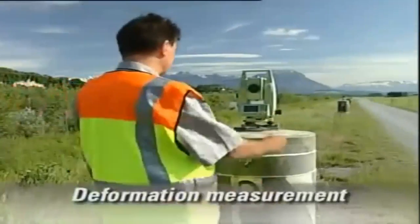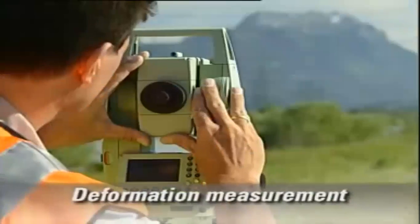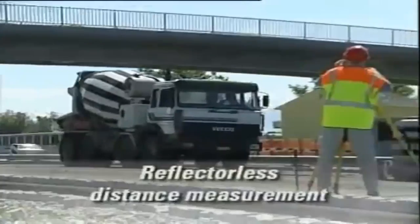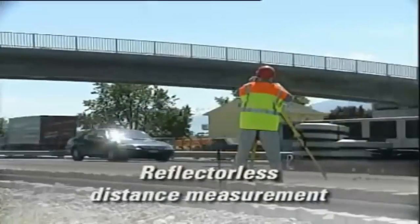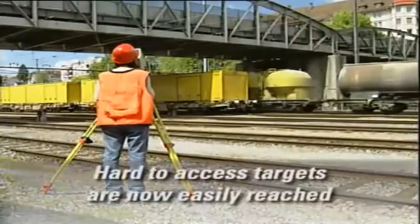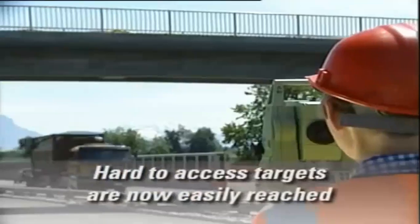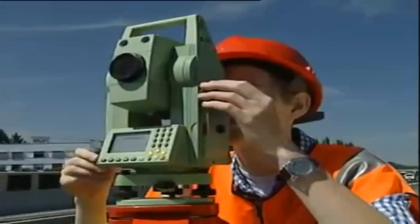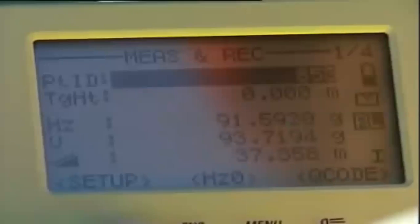For deformation measurements, ATR performs the repetitive and time-consuming task of precision target tracking, easily and quickly. Surveyor's daily nightmare: hard to access targets, obstacles in the way, time-consuming, nerve-wracking, and hazardous work. The reflectorless distance measuring instrument brings relief. With the visible laser dot, surveys are performed quickly and safely. Aim the laser at the target to be measured, trigger the measurement, and read off the measured value.